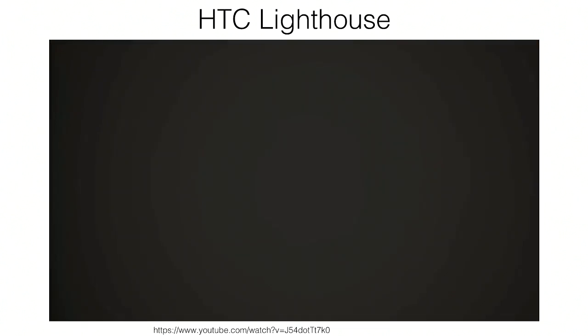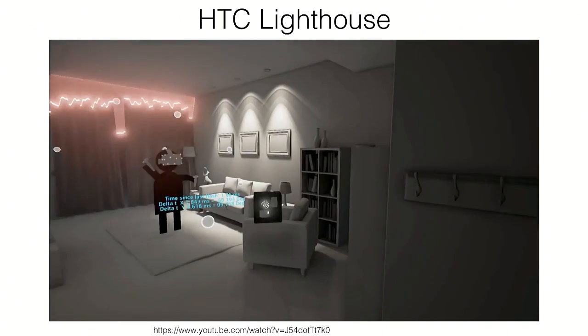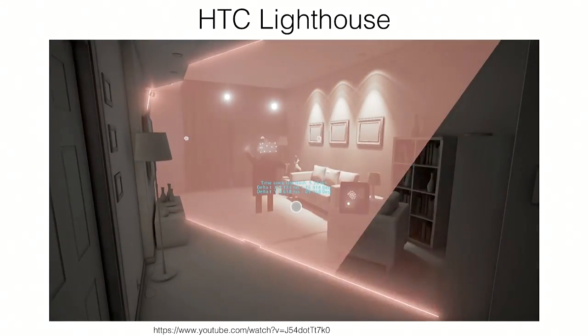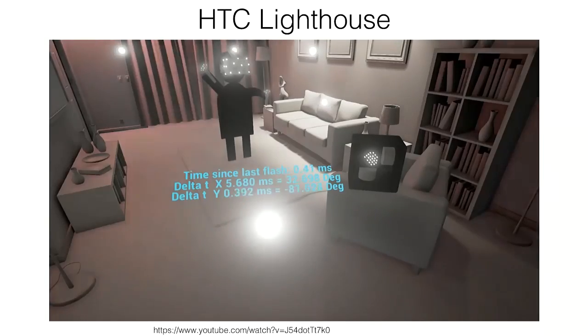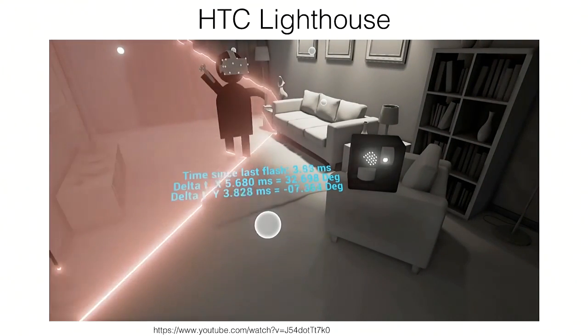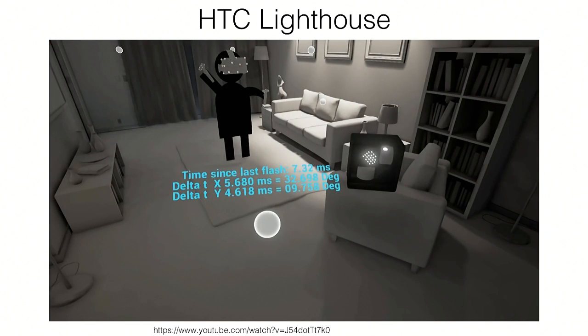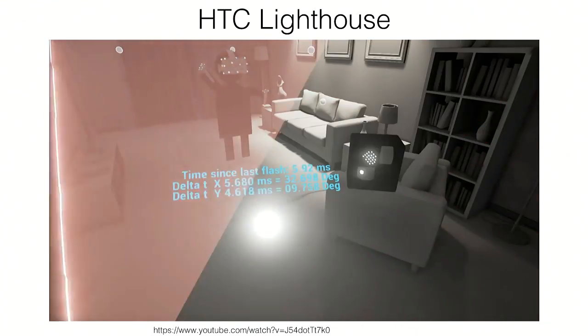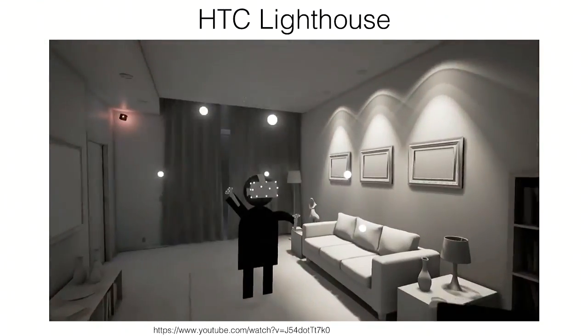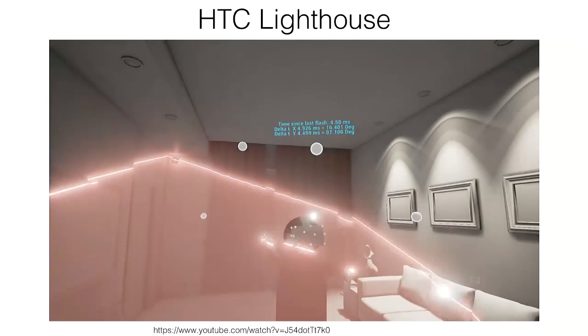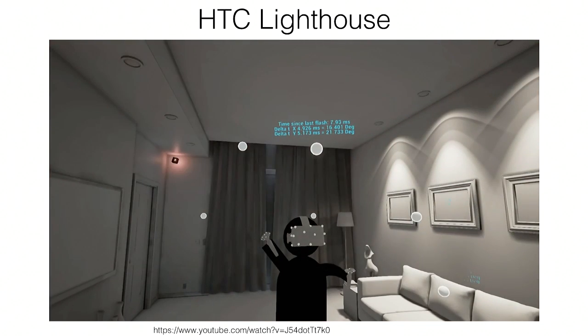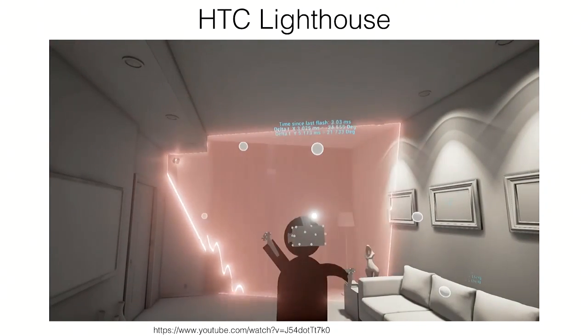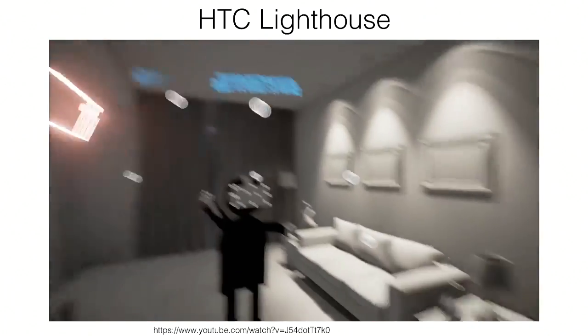So here's the animation. I think it makes it quite intuitive. So here's a sweep, horizontal sweep. And then each of the photodiodes measures the relative timing from the sync pulse. So the sync pulse is going to be this. Sync pulse, now comes the sweep. Each photodiode has a slightly different timing, right? And you have the sync pulse in between each of the sweeps. Right? Is that reasonably clear?